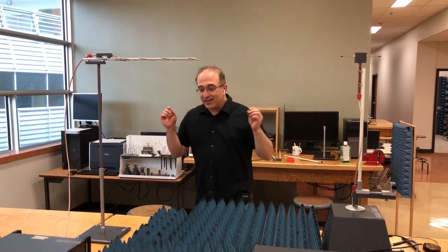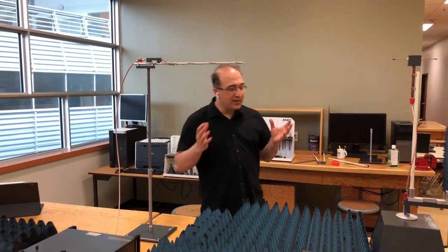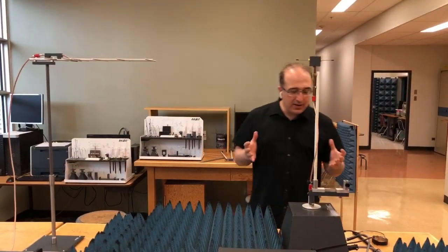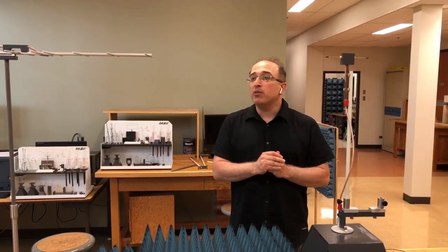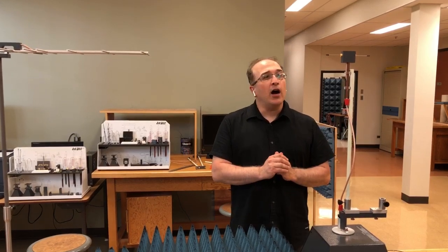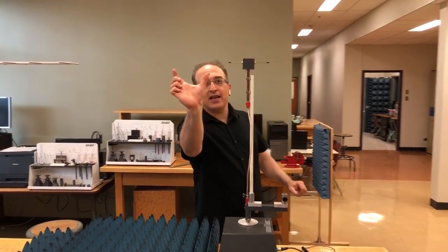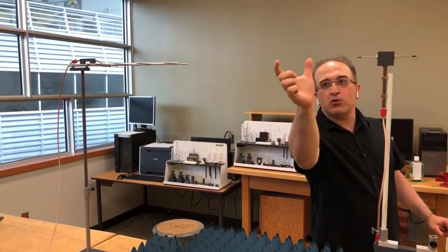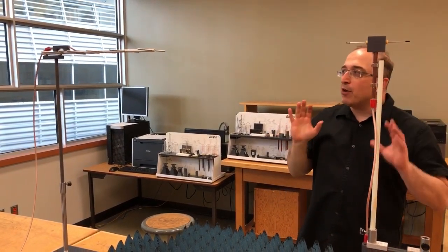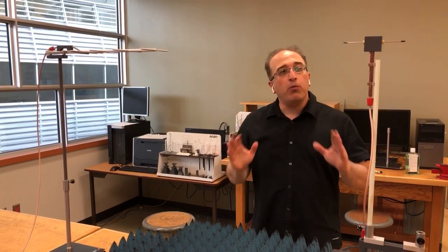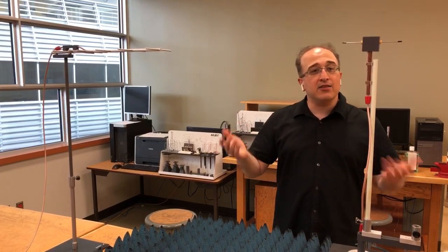Okay, so the previous measurement was essentially E-plane cut. This is a very important cut, E-plane, and the other one, H-plane, that we're gonna see. But before going to H-plane, I want to also talk about one other thing in E-plane. So when this dipole antenna that we had rotated like this, that was our E-plane measurements. But now, if I want to be more accurate, that was co-polarized E-plane, because the dipole antenna had the same polarization as the transmitting antenna.